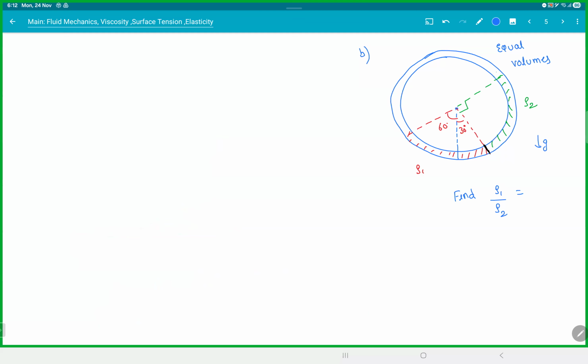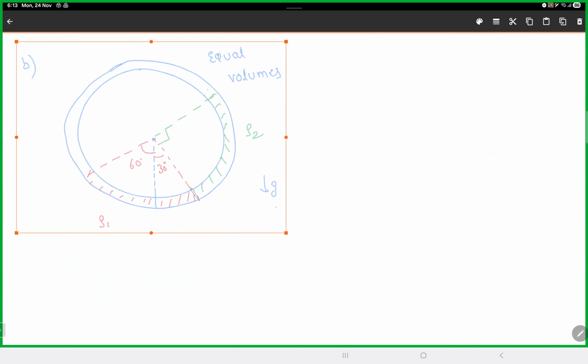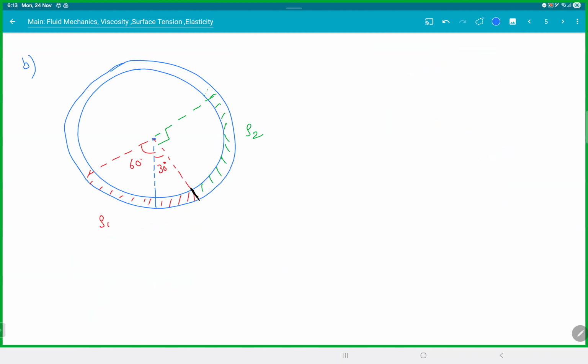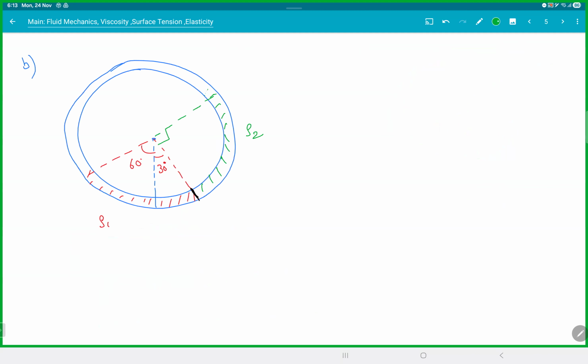So here the idea is the pressure always depends only on the vertical height. It doesn't matter what the shape is. So when you take the height, again same thing here, I will choose 2 points here. Let's call this point A and this point B. Since the system is in equilibrium at that interface, PA is equal to PB. The 2 points are touching and they're almost there.